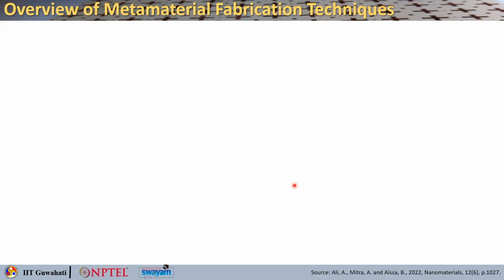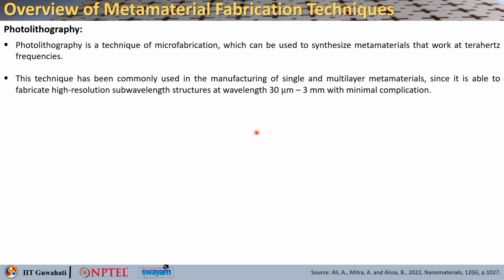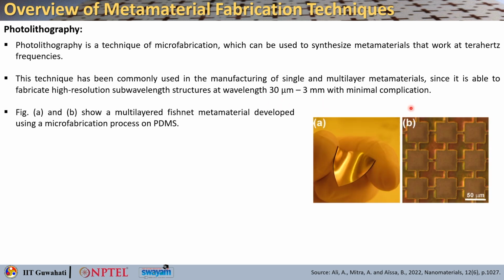Now, with that let us move on to some overview of the metamaterial fabrication techniques. We will just briefly talk about those. So, the first technique is photolithography, a technique for microfabrication which can be used to synthesize metamaterials that work at terahertz frequencies. This technique has been commonly used in making single and multi-layer metamaterials, since it is able to fabricate high resolution sub-wavelength structures at wavelength range of 30 micron to 3 mm with minimal complications.